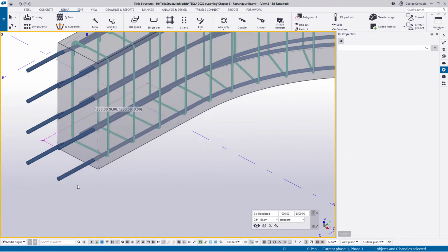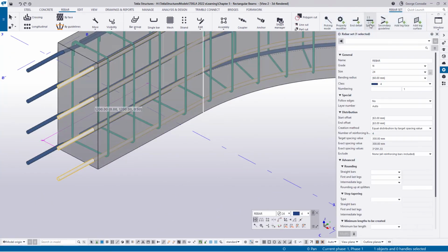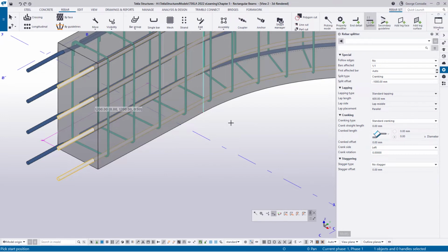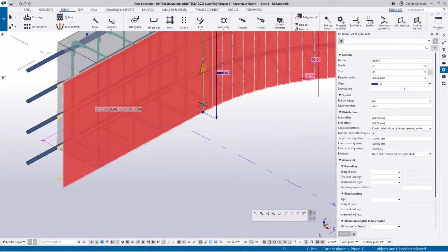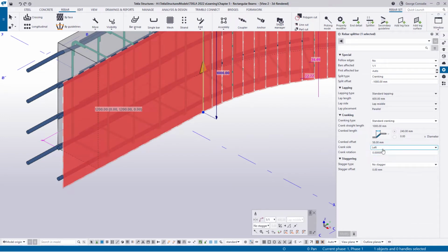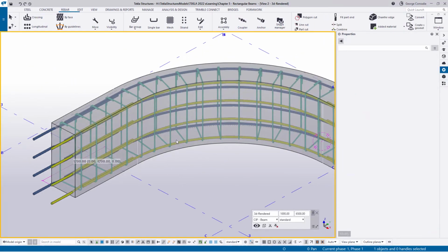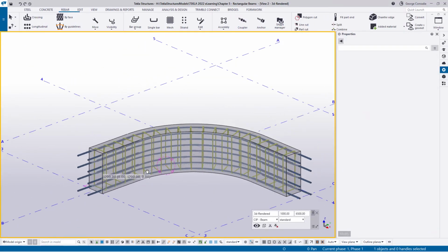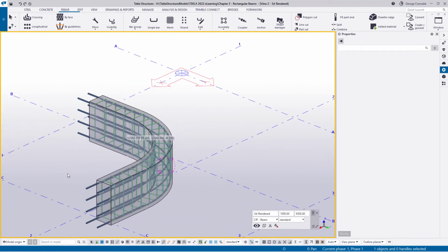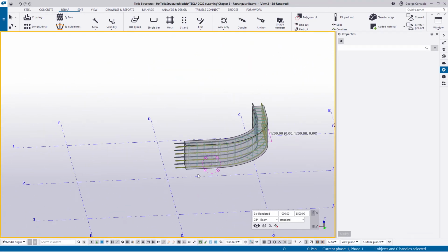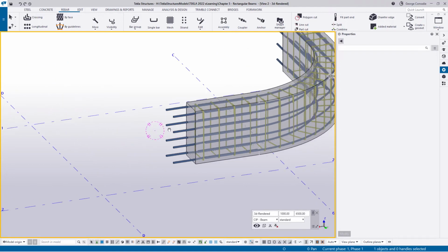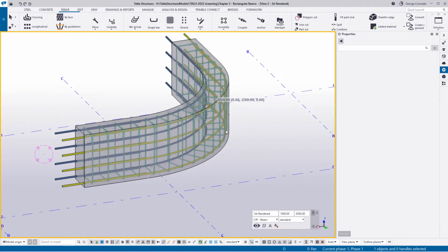And if we go over to this one, we can do the same splitter on the tangential line. It's a problem. Click on the splitter, flip the switch to the other side so it can actually fit in the crank. And there we go. We now have all our bars cranked and everything is good. Now, what we do normally with these beams, we have distribution steel on the side of a different size. Now, what I'm going to do is I am going to do that, but I'm going to do it after I insert some center bars.